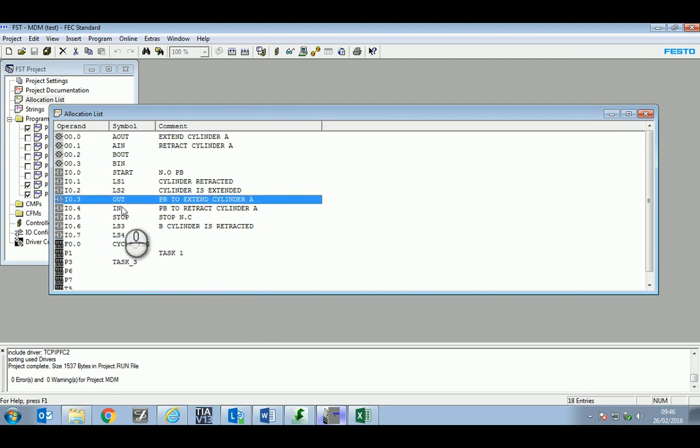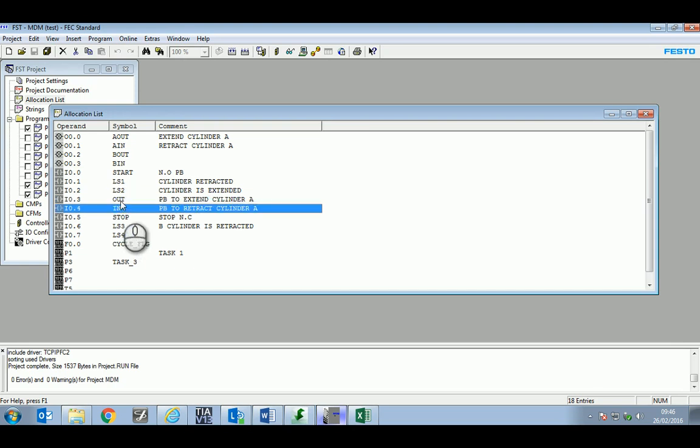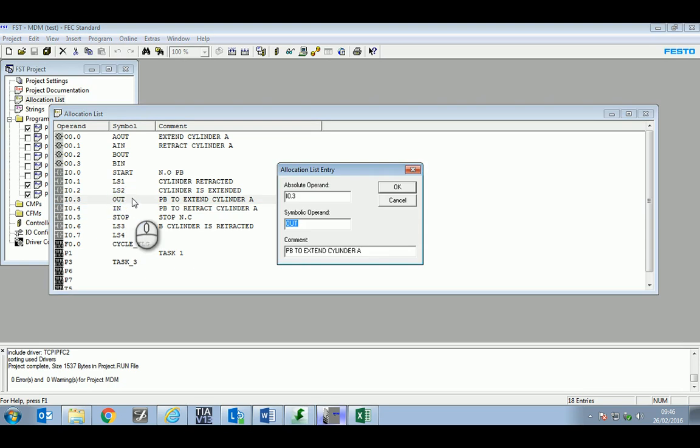What's no longer being used are 3 and 4, your in and out button to make the cylinder move, which was used for the previous example. So we need to reuse one of these, and I'll call it, let's put in caps, EM STOP. We'll make it normally closed. So you need to wire up a third push button now that is normally closed. You can use the D10 switch on your button box for that.